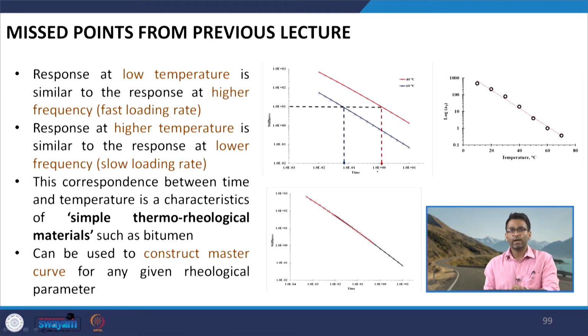Coming to this slide regarding the time temperature superposition principle, I explained that this principle is applicable for linear viscoelastic material, and we discussed how the response at different temperatures can be superimposed to a reference temperature by multiplying the time with a shift factor. So, there is a horizontal shift which we have to apply, and the time or the frequency, whatever the x axis is, has to be multiplied with a shift factor in order to shift the curves from one temperature to any given reference temperature.